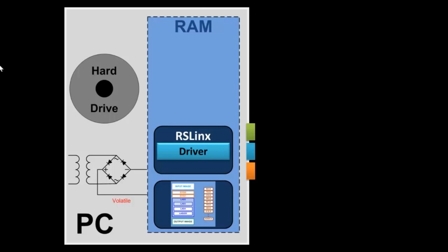This little framework down there called Emulate, once it knows who it is, in other words, I'm a Micrologix 1000, that's sufficient. Now it's something that you can connect to from RSLinx. You can't go through RSLinx out through a cable out to something that doesn't know what it is, because it can't talk back. When you set up the driver with RSLinx, it sends out information. If it gets nothing back, it says, hey, there's nothing out there. So now you're going to connect up to the Emulate frame in your personal computer's RAM with RSLinx.